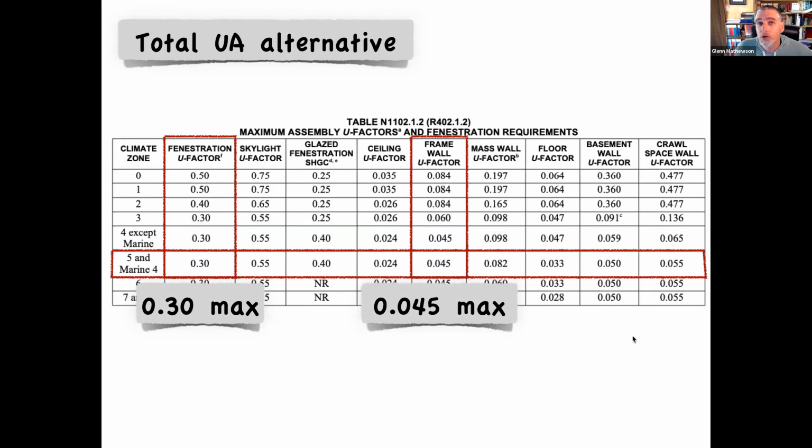When we took the reciprocal of that, it was like R22. If we take the reciprocal of 0.3 U factor for that window, that's like an R3, right? Just a little over an R3. So we understand in construction, our windows do not have the same resistance to heat movement, or in U factor terms, they allow heat movement through much more rapidly than our other insulated assemblies.